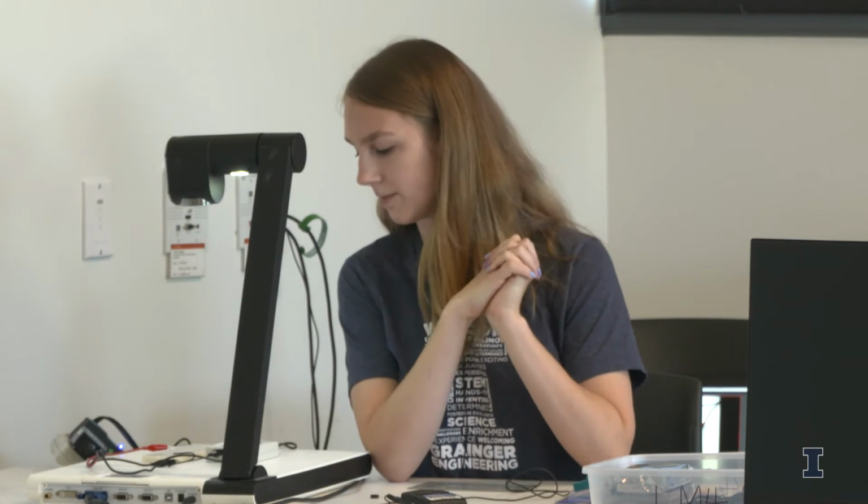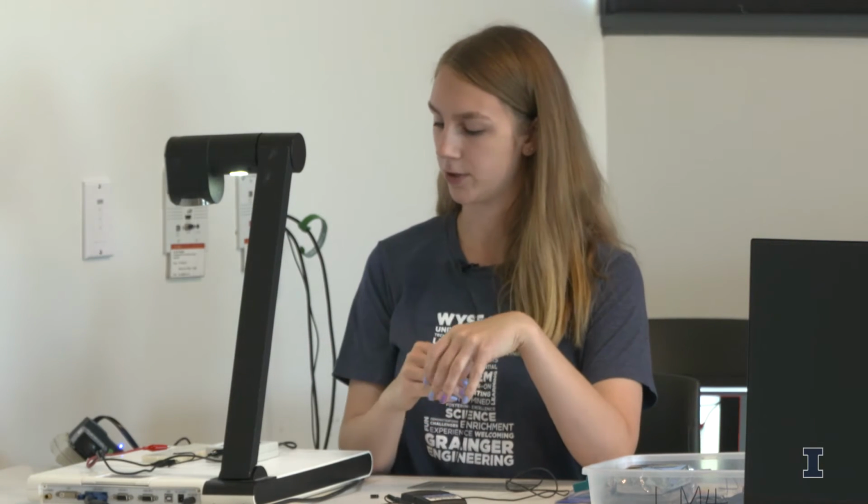So you mentioned that the oscilloscope allows you to view waveforms as a function of time. Does your signal need to be periodic to be able to look on the oscilloscope? Can you talk about what types of signals you can measure, or typical voltage ranges, and so forth? Yeah. So you can measure both alternating current and direct current. If you measure direct current, you should just see a line because the voltage is staying the same across time.